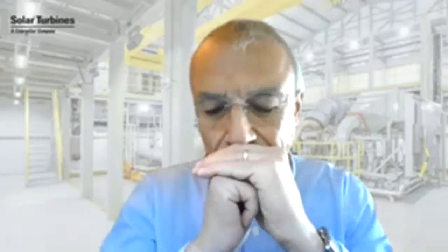And what advantage does that create, Rainer, the low-speed balancing capability? If you have to do high-speed balancing, you need what's called a balancing bunker, and there are not that many around in the world. So you would be very much limited to very few facilities that can actually do this high-speed balancing. Okay, great. Thanks for that follow-up question.